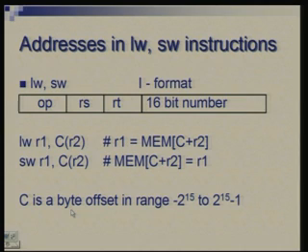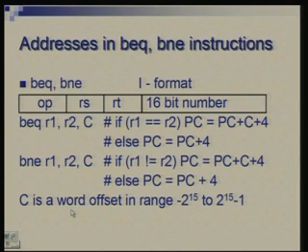And the address which is being specified here is a byte address. In BEQ, BNE we will actually have, we are worried about word address. So, whereas data could be in terms of bytes or words or double words or half words, all those varieties may exist. Instructions in this architecture are all one word instruction.